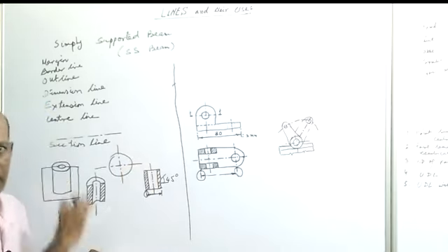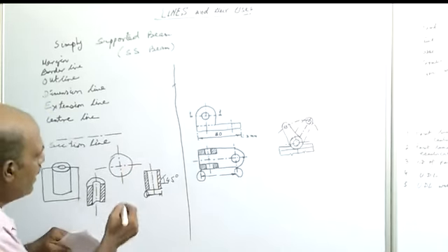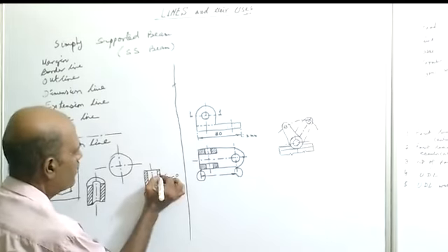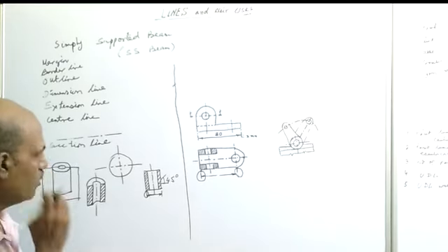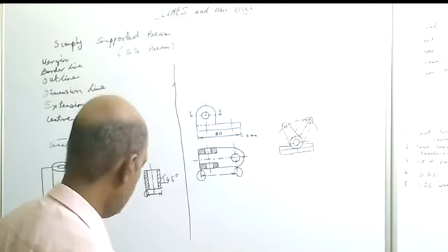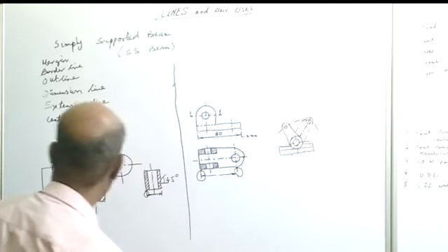A uniform gap, 2 to 3 millimeter, and this is a thin continuous line, and the gap maintained is 3 millimeter. So this is the hatching line. Next will come the hidden line.